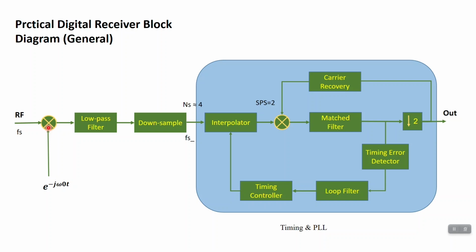The first step is to drive a DDS or NCO by the carrier frequency of the signal, to transfer it to baseband. As you know, after the DDS you have other harmonics also, so you need to keep only the baseband harmonic. So you have to use a low pass filter for this reason.